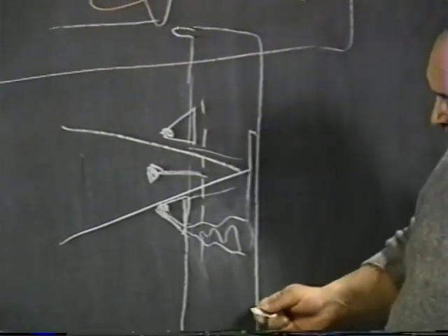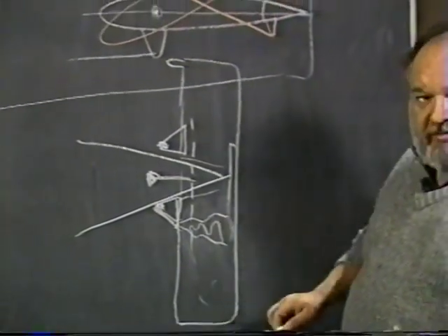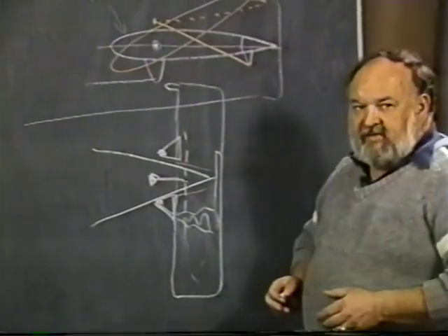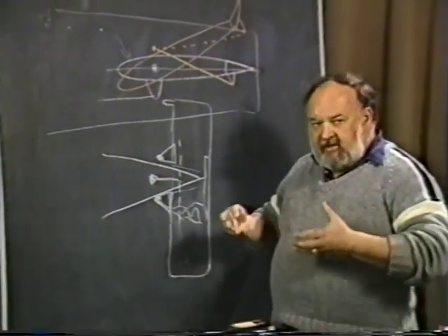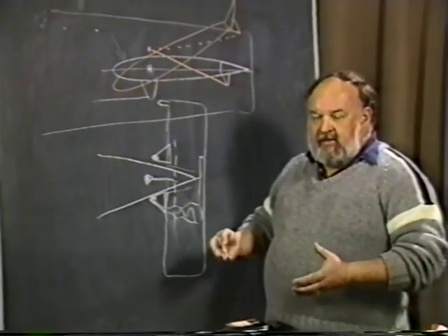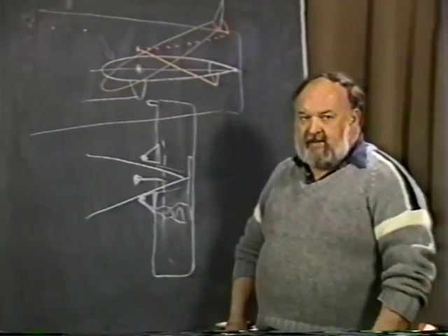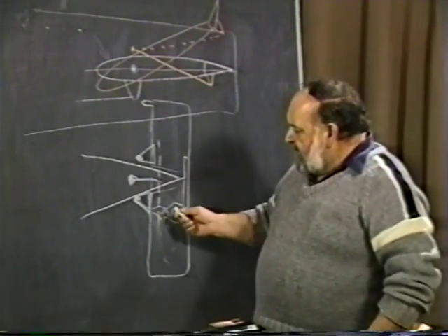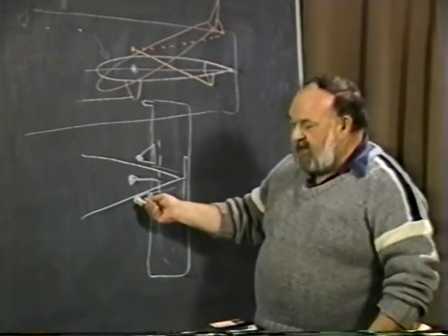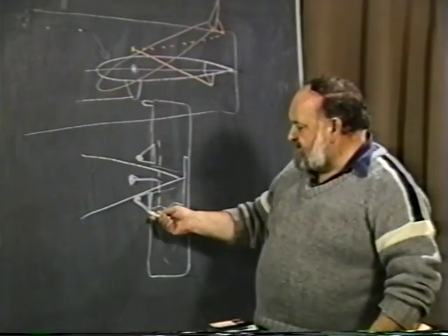Maybe if you got very high and very excessive, the outboard section might stall, but a major portion of the tail still had energy to it, still was producing a download, and it was not any kind of severe reaction where the airplane would then pitch over very violently as the tail surface would stall. This has that advantage, again, that you can put your mass balance into it, you end up with a nice